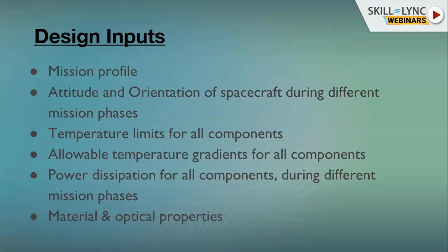Then it is important to know what materials are being used in the spacecraft and their optical properties. So most of the time for passive thermal control, the designer will tend to use the surface optical properties of the material itself to reach adequate thermal control. So all these inputs are required from the thermal design point of view before you start the thermal design.